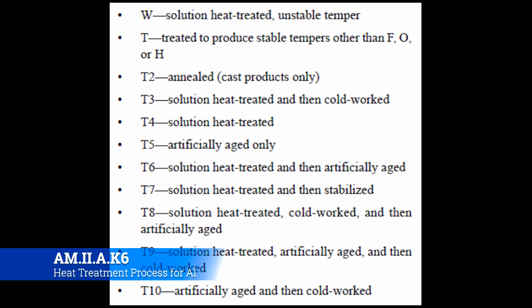If for any reason this identification is not on the material, it is possible to separate heat-treated alloys from non-heat-treatable alloys by immersing the sample material in a 10% solution of caustic soda. The heat-treatable alloys turn black due to the copper content, whereas the others remain bright. In the case of clad metal, the surface remains bright, but there is a dark area in the middle when viewed from the edge. All right, so that's out of the 8083. There is a way to start to tell these apart. I'm telling you, just as an aircraft owner, mechanic, and pilot, don't do that. Just bite the bullet, order the metal that you need, and then take the rest to the scrapyard or sell it to somebody with a little bit less standards.